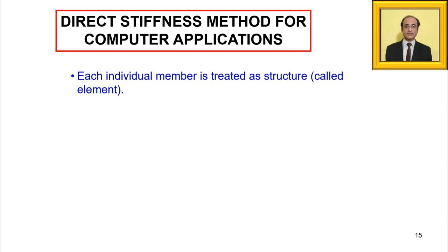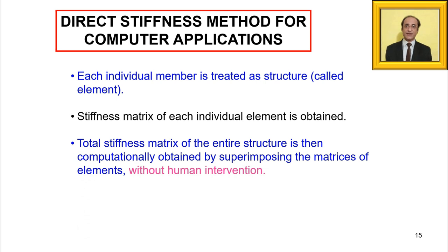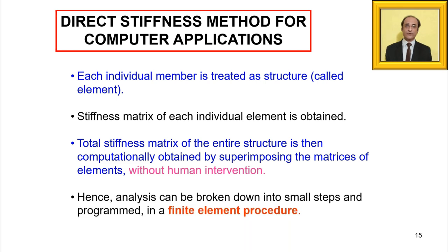Finite element approach means that we begin with a small element and set up the equations, say compatibility and equilibrium of that element. So element by element we form equations and then assemble all the equations together such that we get the requisite equations of the whole structure. That is finite element approach. All the finite element software works on that approach. So basically it has widespread applications in various domains.